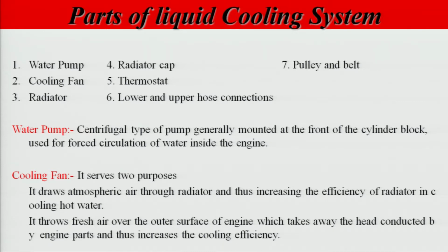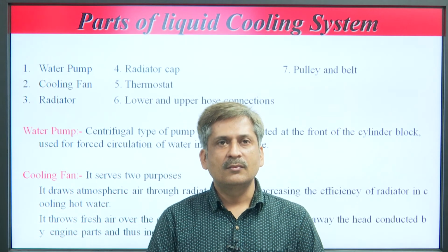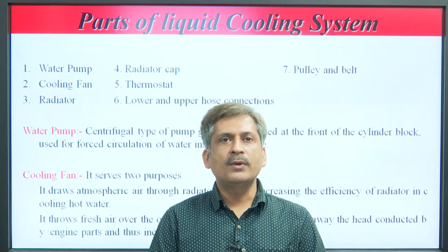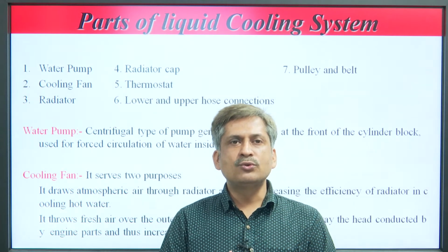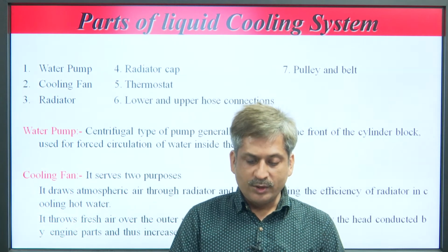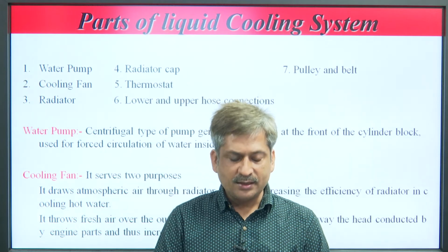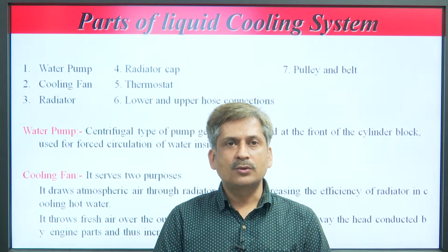In the last lecture, I showed you the slide for the water pump forced circulation cooling of the engine. So, water pump, then cooling fan. It serves two purposes. It draws the atmospheric air through the radiator and thus increases the efficiency of the radiator in cooling hot water.